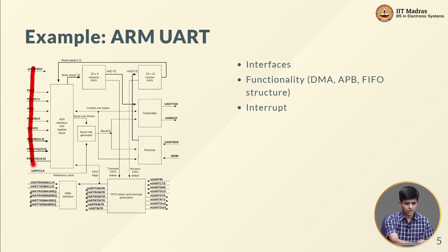One is that there are a whole lot of input and output interface pins associated with a device like this. You might think that a UART is actually a very simple device. After all, it is essentially supposed to be a 2-pin device, just one transmit, one receive, and on the other side there is a FIFO buffer. But as you can see over here, there is a reset, there is a clock, there is another reset which is perhaps for the peripherals. There are a bunch of select, enable, etc. signals. There is also something that allows you to write into this, and the data. All of this essentially provides some kind of a bus-like interface.